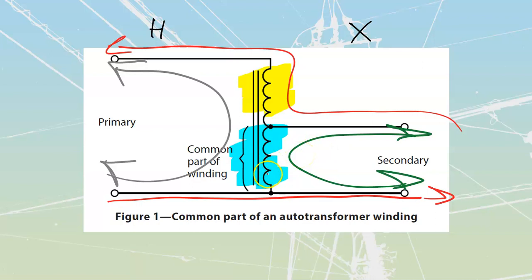How it works is that we have energization of our coils. That energization of the coils is going to create magnetic flux. That magnetic flux is going to enter the core, that's what these two lines represent, and is then going to get transferred back to the next section over here. So it's still working through the same principles of electromagnetism. We are fluxing up that core and then dumping that flux in, cutting across the conductors on the other part of the transformer to create values of voltage.